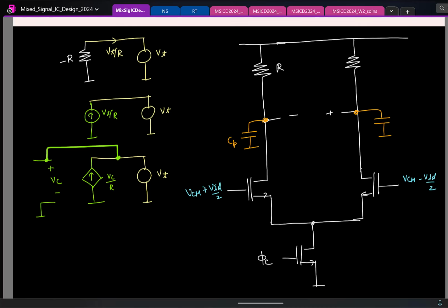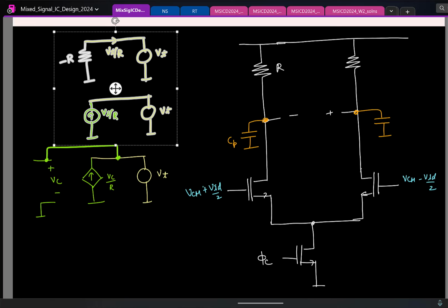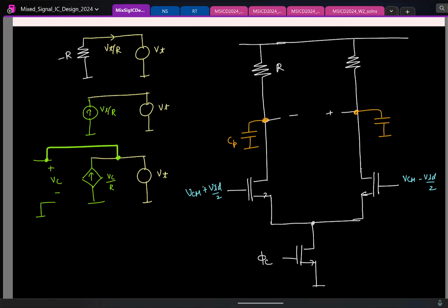So that's still hypothetical. So do you know any voltage controlled current source? A transistor is a voltage controlled current source in small signal. So let's draw and see. If I draw the incremental equivalent of an MOS transistor, it's going to look like this. This is the gate, this is the drain, this is the source.